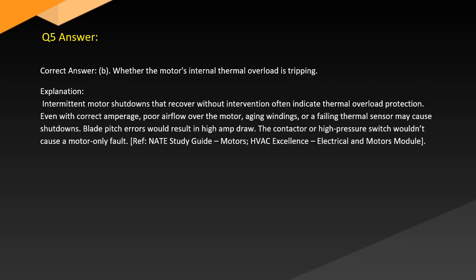Answer. Correct answer: B. Whether the motor's internal thermal overload is tripping. Explanation. Intermittent motor shutdowns that recover without intervention often indicate thermal overload protection, even with correct amperage. Poor airflow over the motor, aging windings, or a failing thermal sensor may cause shutdowns.